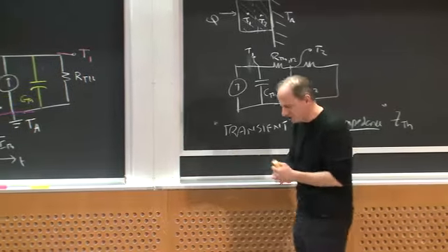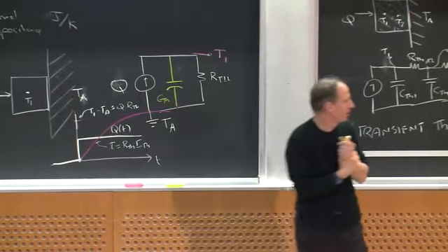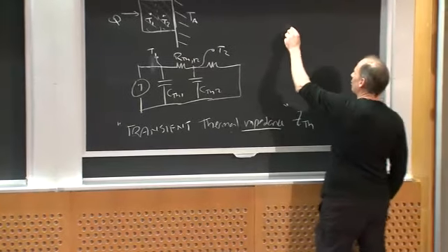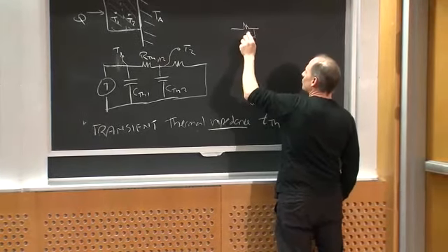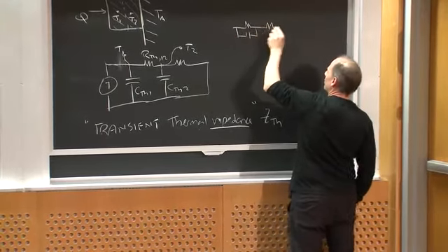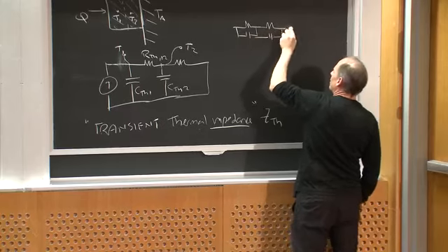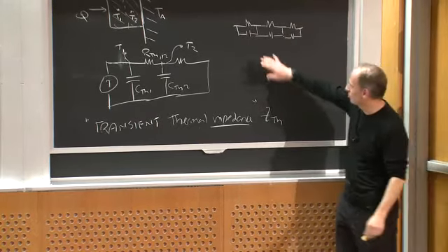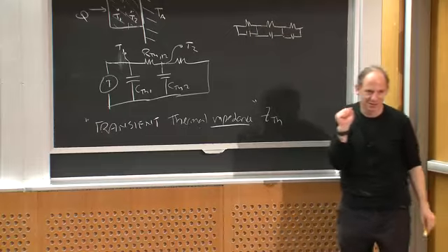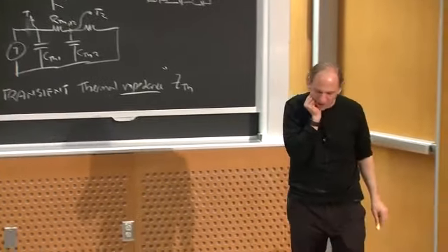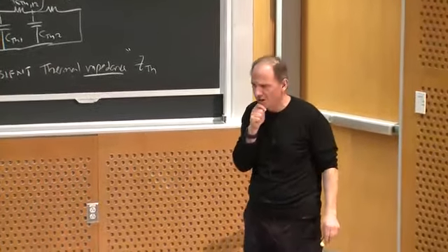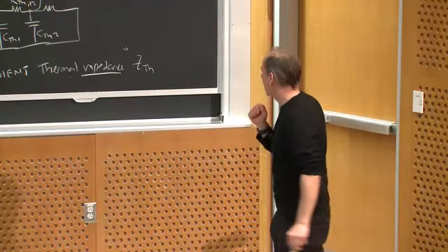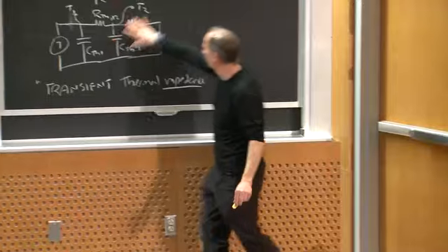You will often see thermal models. This is called a Cauer form network. You will often see thermal models in data sheets or app notes or something that are something like this, okay? And that are done like this. So thermal resistances and thermal capacitances. That's sort of a Foster form of network. That's just wrong, unfortunately.